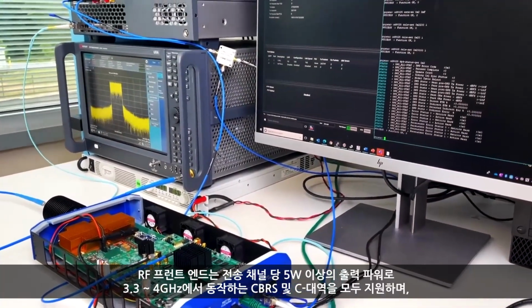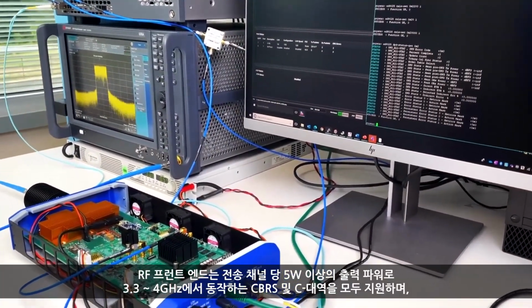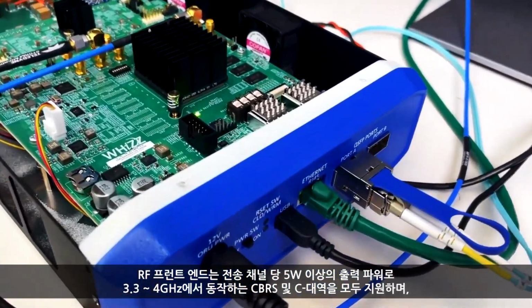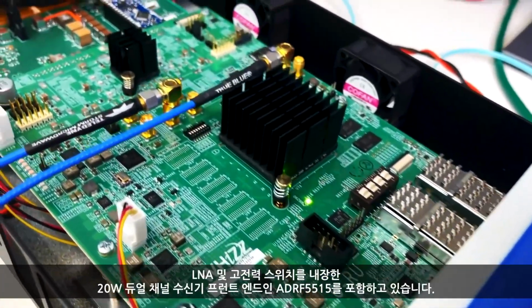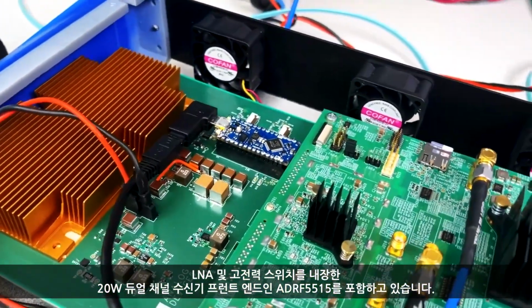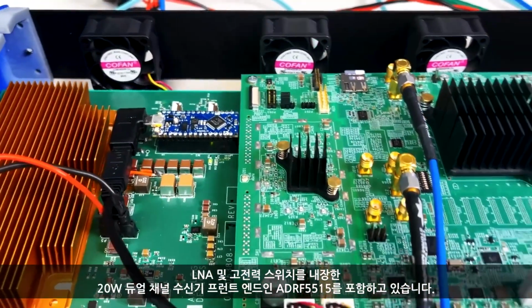The RF front end supports both CBRS and C-band operation from 3.3 to 4 GHz with 5 watt plus output power per transmit channel and includes the ADRF5515, a 20 watt dual channel receiver front end with integrated LNA and high power switches.